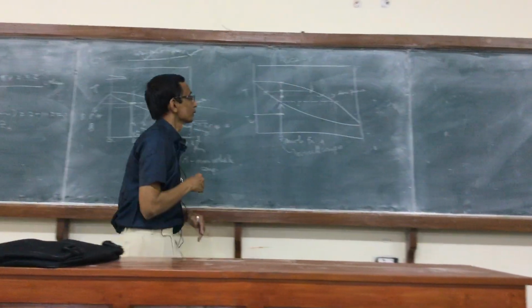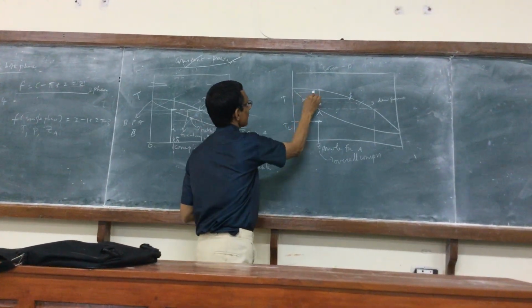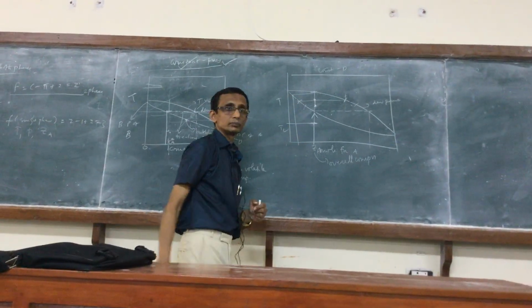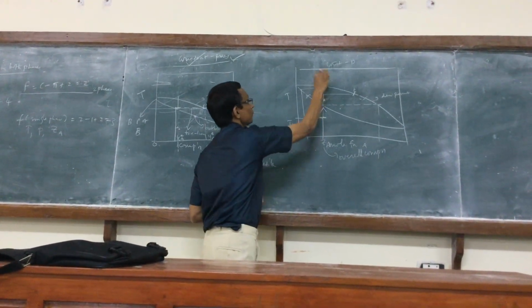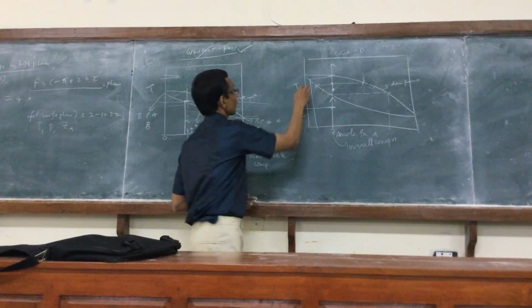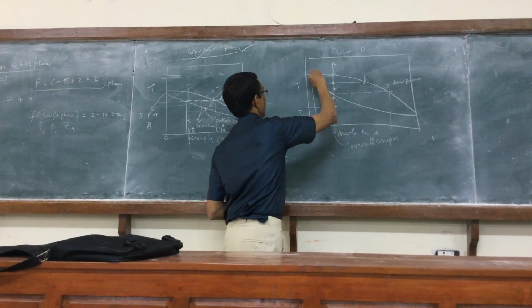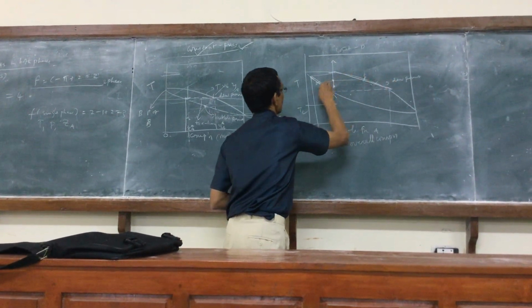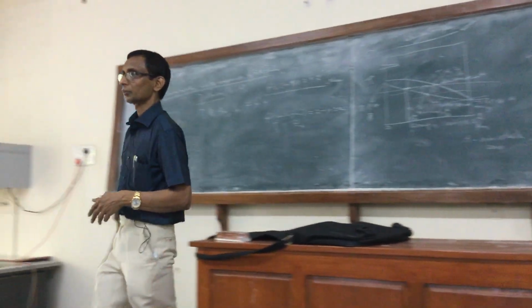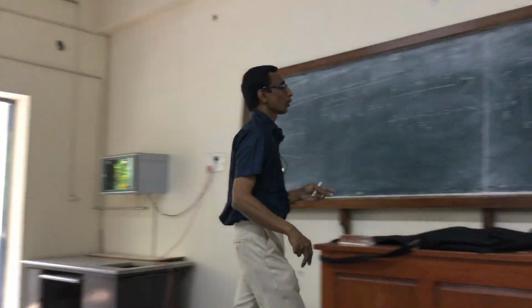At that point, all the mixture would have been effectively vaporized, and this can be regarded as the composition of the liquid at that point. After which it will entirely become superheated vapor, or you can call it gas. So the liquid composition will move along this envelope. The corresponding vapor compositions would move along this envelope. All this you must be familiar with from your earlier courses on mass transfer and so on. So this is what happens.